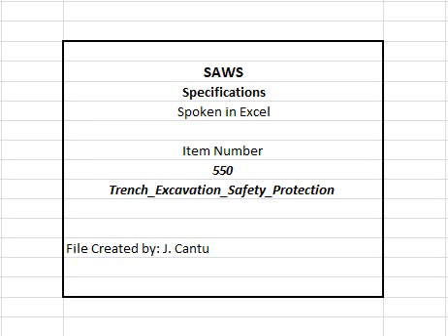4. Submit certification that trench safety system will not be subjected to loads exceeding those which the system was designed to withstand according to the available construction and geotechnical information. 5. An excavation plan submittal signed and sealed by a Texas licensed professional engineer shall be submitted for review and acceptance by the SAWS representative, if applicable, prior to the delivery of materials and commencing any portion of proposed construction activities where the planned excavation is 20 feet or greater.